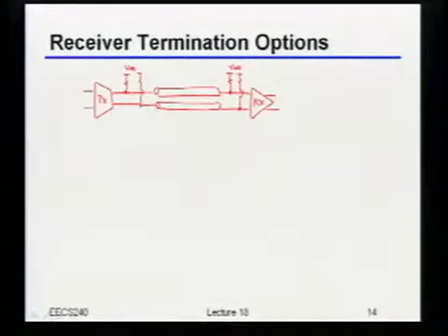So what do you mean when you use MOM capacitors? You mean you put a capacitor with the bottom plate capacitor? Exactly. I'll just sketch it right here real quick. If you put in an explicit cap for yourself, because you decide you want some extra explicit cap, which, by the way, you may or may not need here, what you should do is add the top and bottom plate capacitors to ground, and you can use the parameters for how much those should be based on that capacitor homework that we had. The solutions are still up on the web, so if you got the wrong answer, go and take the parameters from there.